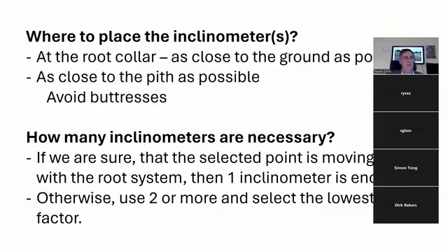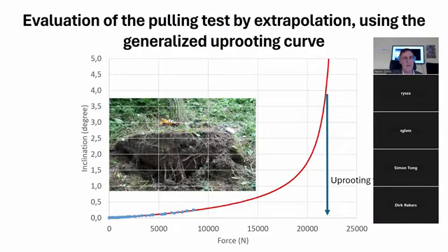In that case, we need to use more sensors too in our system. But if you are unsure, you can repeat the pulling test after 15 minutes, placing the sensors at other locations and compare the test results. Please wait around 10 to 15 minutes between two pull tests.